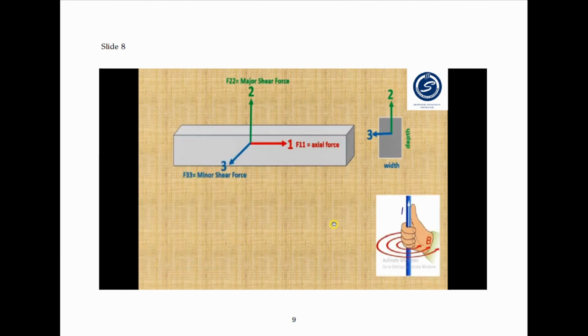After taking you through all these details, they are very, very important. The local axis is very, very important in ETABS because we use it to interpret our analysis results. Since axis 1 always points along the member direction, it will always refer to the axial force, so it is called F11.